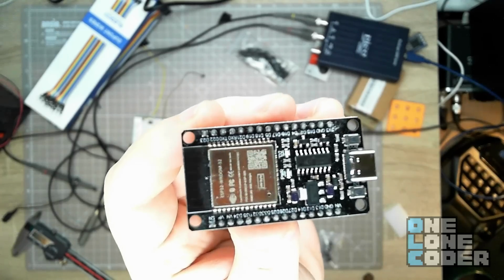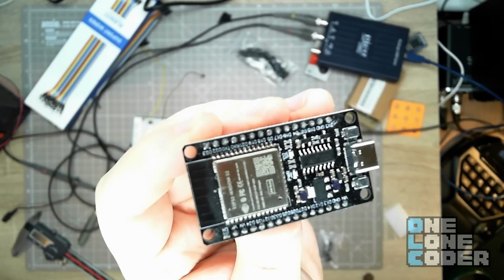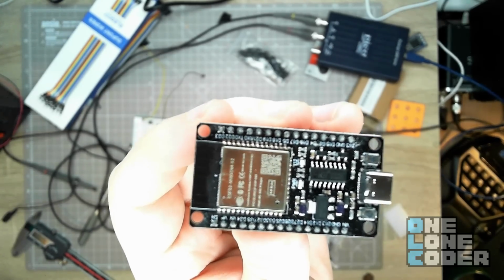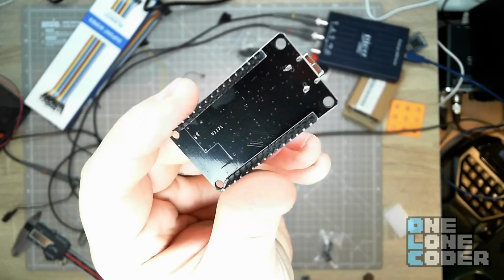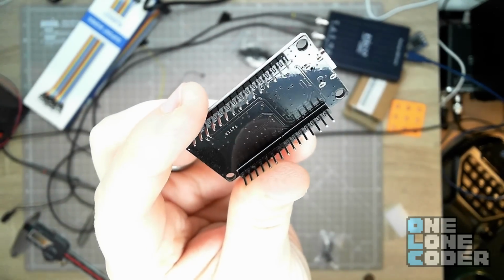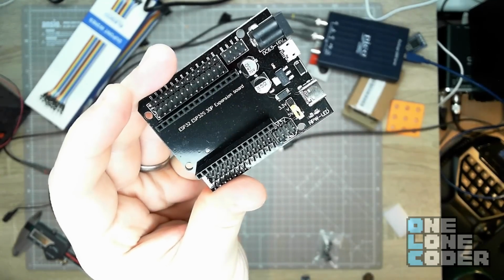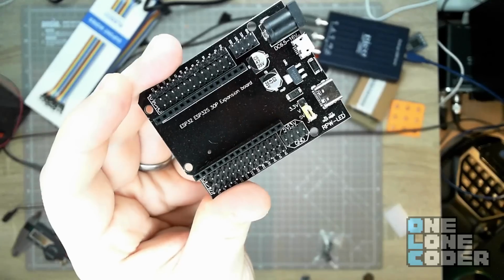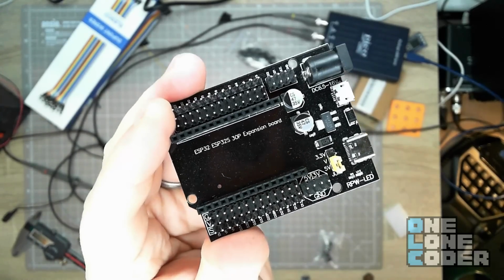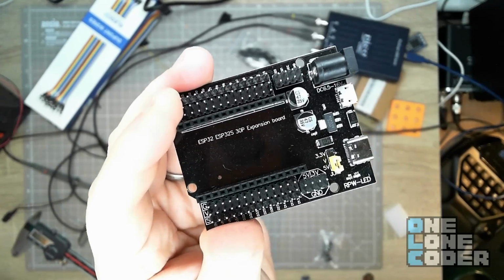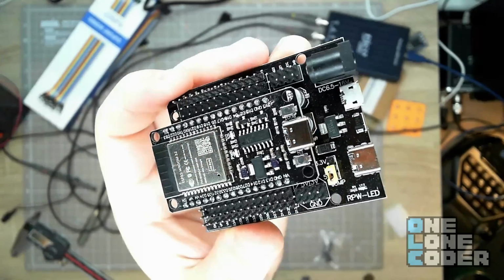And it's pretty cool because it comes with a reasonably good processor clocked at about 240 MHz, and it's got integrated Bluetooth and Wi-Fi modules and a USB-C connector. It also has easily accessible GPIO via all of these pins. And in fact, I bought to go with it this breakout board, which makes accessing all of those pins even easier, but it also allows me to plug it into a power supply. The breakout board, in fact, came with the ESP chip, so the whole thing combined was about £7. When the two are mated, it's a little bit smaller than a credit card.